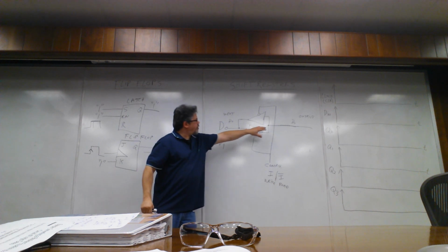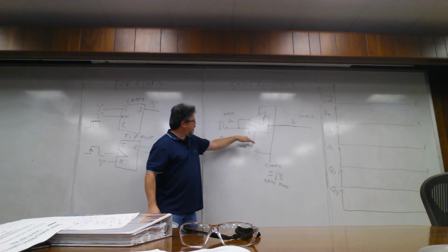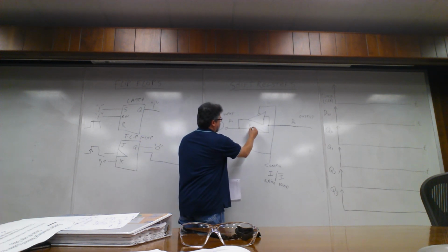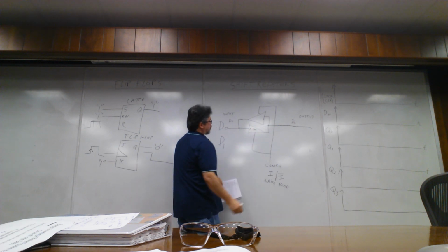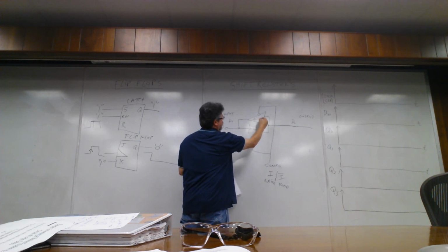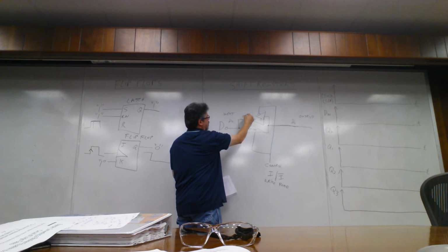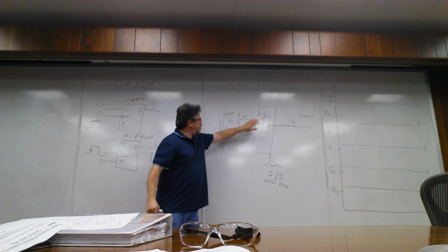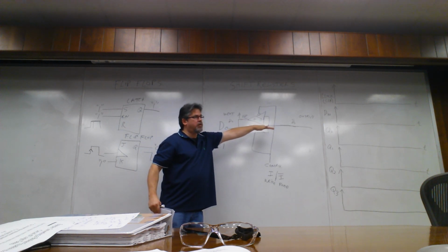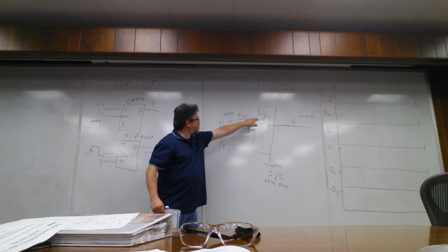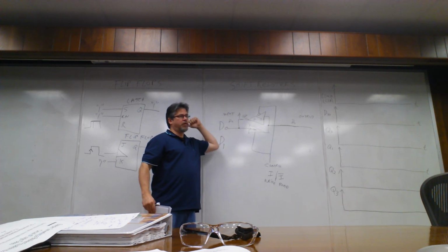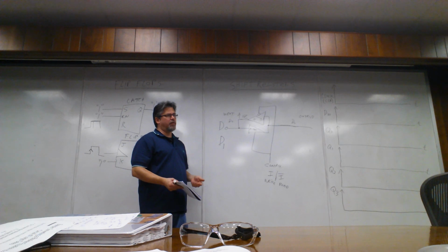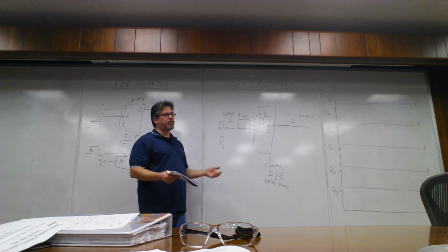So basically, like I said, you have data moving in one direction or it's moving in the other. If I enable this high, this buffer is like a switch inside, a transfer switch. The switch is closed, so it's allowing data flow this way. This switch is open. This is a high impedance state, high Z. So this one is open, this one is closed, and we have data flow this way. Then if we flip it, if we go low, this one is closed, this one is open, so data flows the other way. So they call it bus transceivers or tri-state communications, that sort of thing.